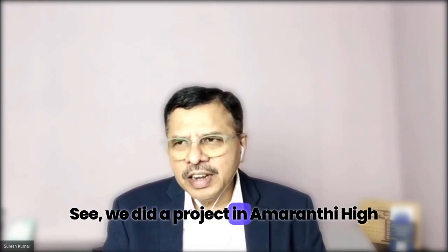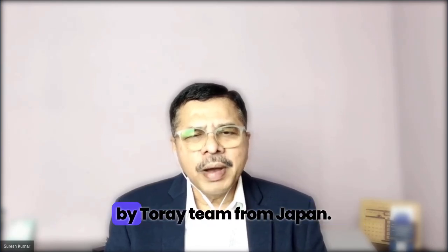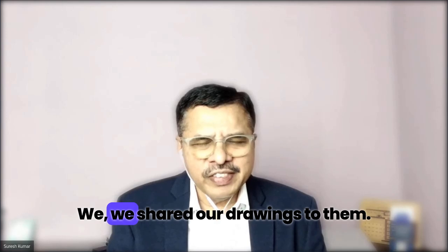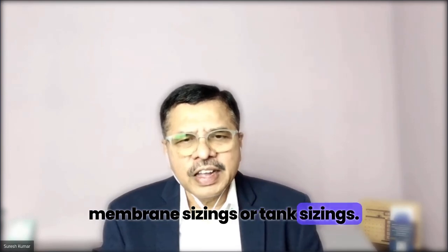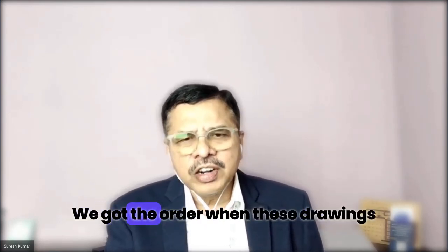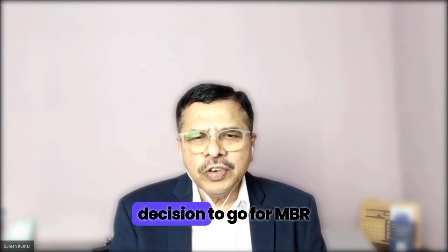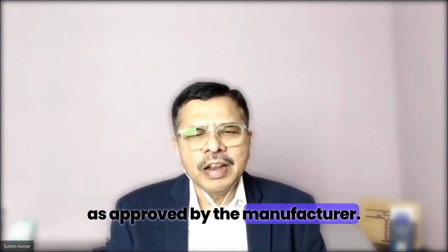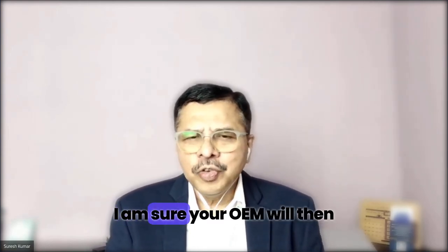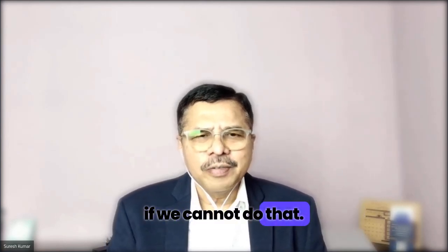See, we did a project in Amaravati, the Andhra Pradesh High Court building, with MBR. We submitted drawings validated by the Toray team from Japan. We shared our drawings with them. They validated our pump sizings, our membrane sizings, our tank sizings. Only when they validated, we got the order, when these drawings were submitted to the client. So please insist, it is an expensive decision to go for MBR, and it should be based on real data as approved by the manufacturer. I am sure your OEM will then give you either the right inputs or he will run away from that place if he cannot do that.